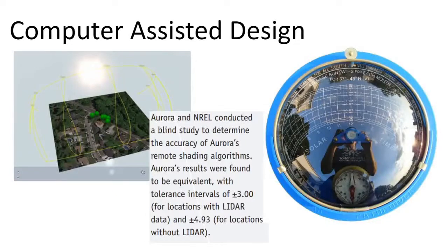So the other drawback of solar design tool is it does not do shade analysis. Trees are tricky, and not being able to model shade because of trees can land you into problems. So it used to be we would get up on the rooftop with a survey tool, and it would kind of read a chart and let us know when the sun's going to shine and when it's not.